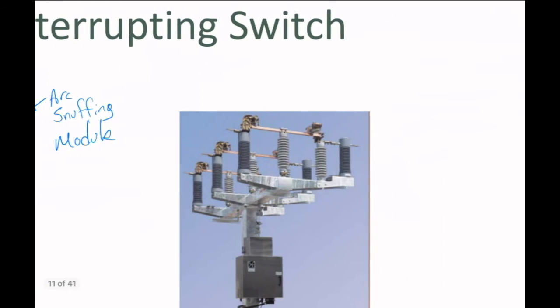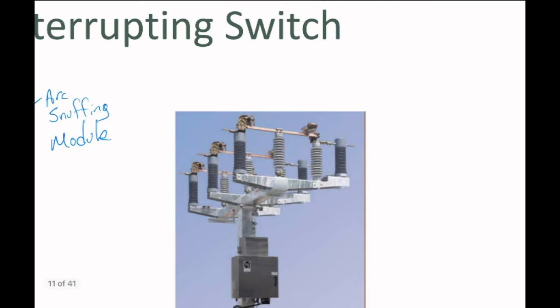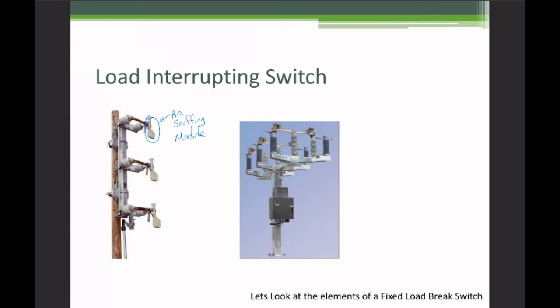Over here in this design, this central bar rotates on operation, and this little bar here is going to swing out and ride as this begins to rotate, and that serves as a secondary break point for the contact so that we don't chew up the primary contacts. However, this is still going to allow for a fairly large and fairly uncontrolled arc compared to other designs.